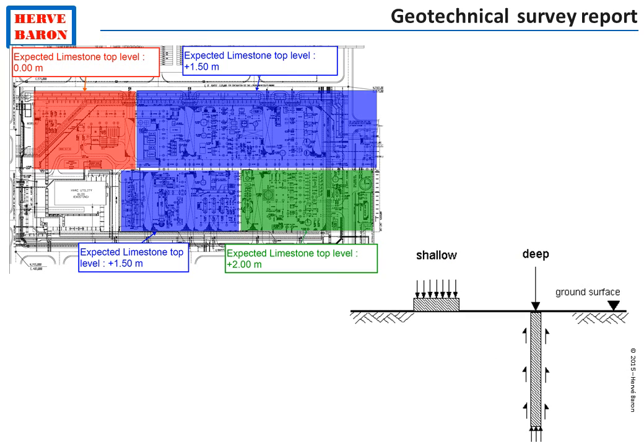The soil investigations also result in the issue of the geotechnical survey report. It contains the design basis for foundations: whether these foundations shall be shallow foundations or deep foundations, and what is the soil bearing capacity? And this allows civil to start with the next activity, which is the design of equipment foundations.